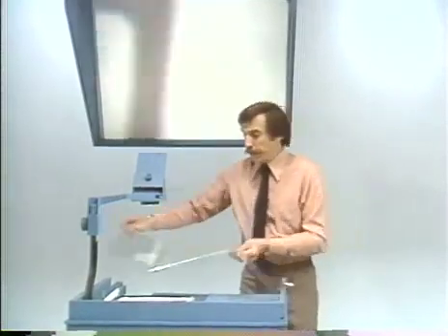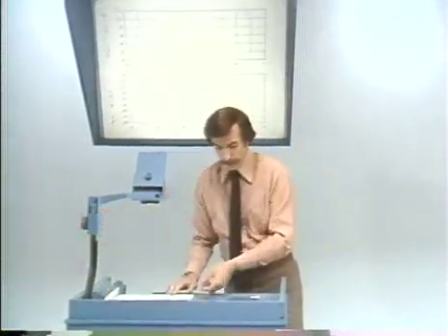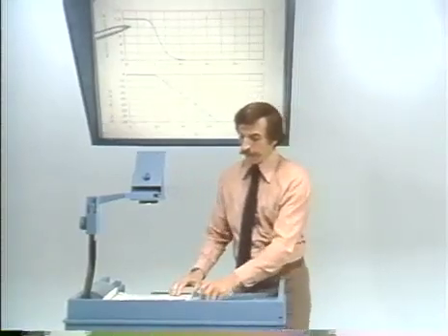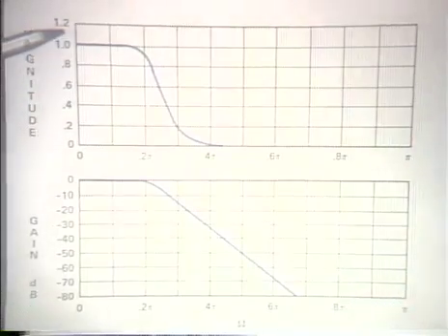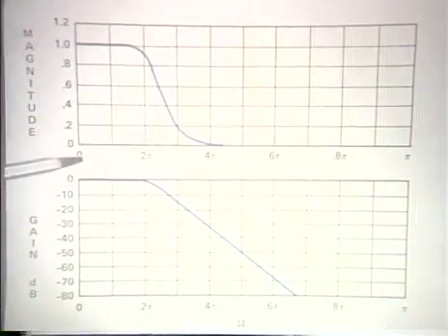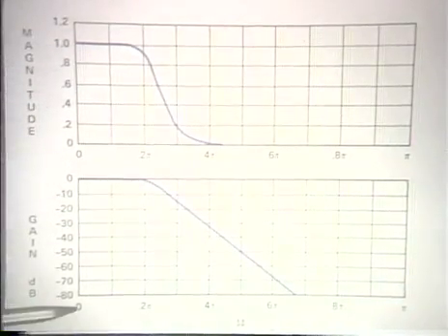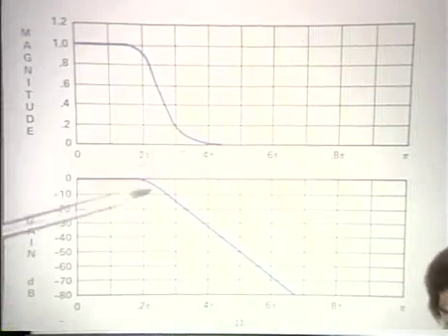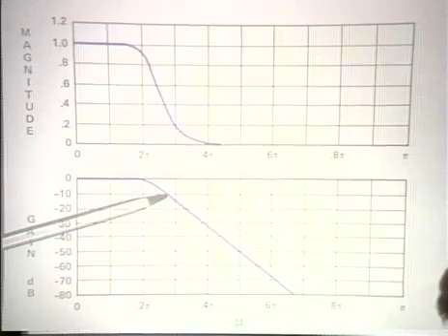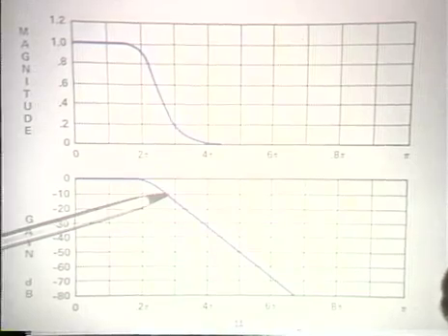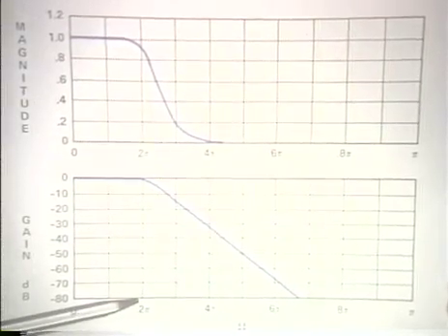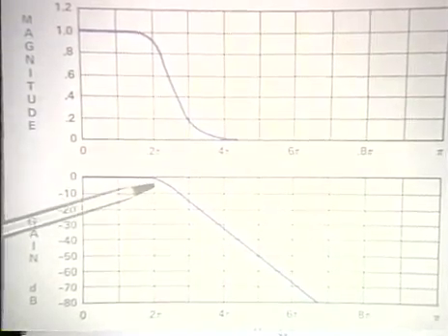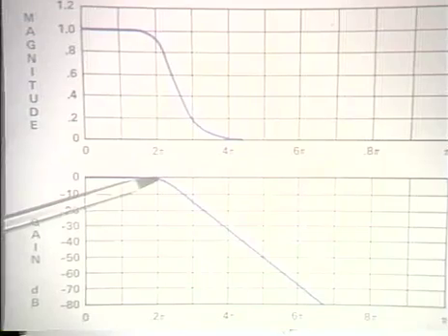All right, well, let's just see what the result looks like when we're done. Here I show again on both a linear magnitude scale and on a logarithmic or dB scale the frequency response of the resulting filter. And recall that the specifications were that at 0.2 pi we should be down by no more than 1 dB, and clearly we've exceeded that considerably.